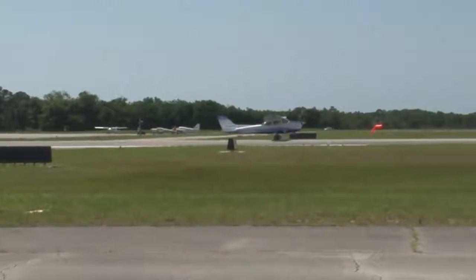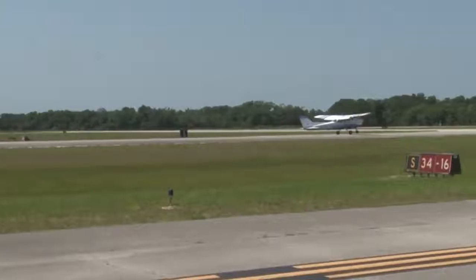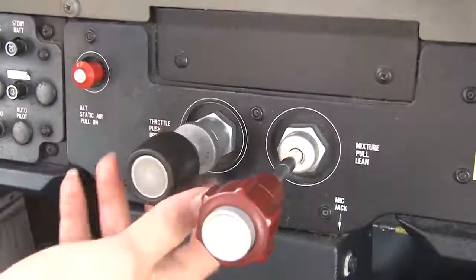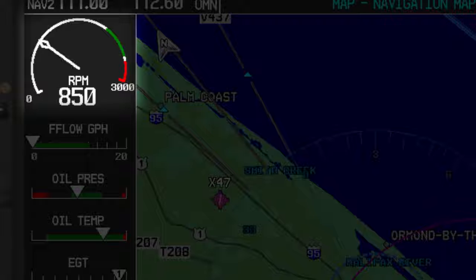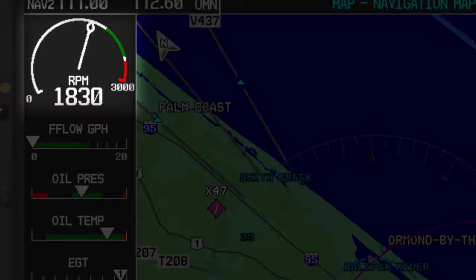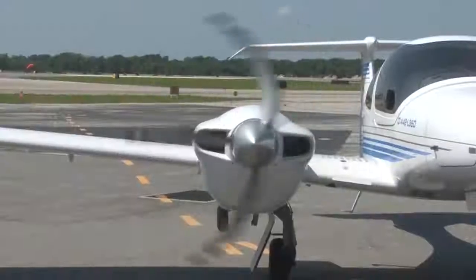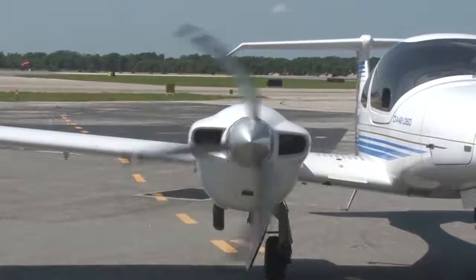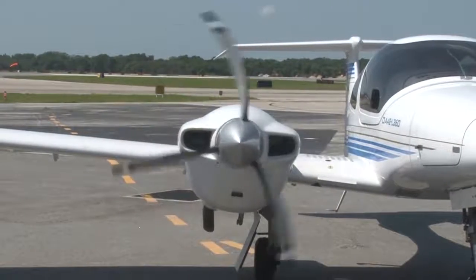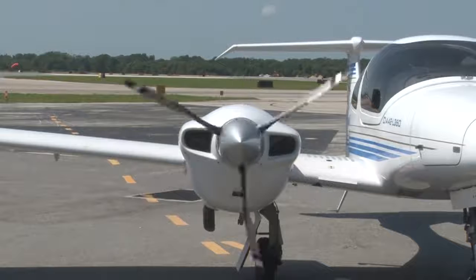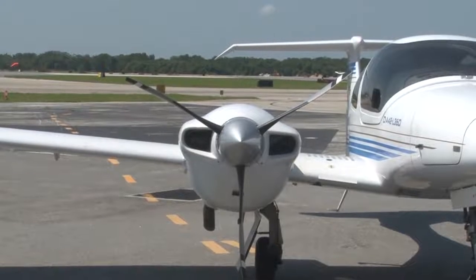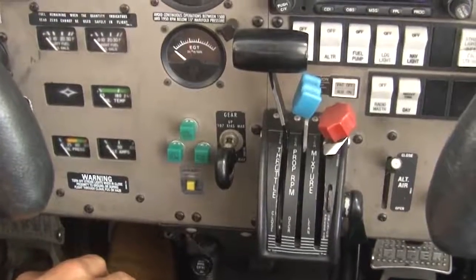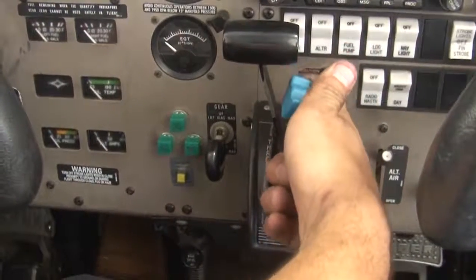It is installed onto the airplane and will always remain exactly how it was installed. An airplane equipped with a fixed propeller only has the throttle to control the engine RPM and therefore propeller RPM. A constant speed propeller, such as the one on the Diamond DA-42, is more efficient than a fixed-pitch propeller. With a constant speed propeller, the pilot can adjust the blade angle of the propeller to obtain maximum performance for different conditions of flight.